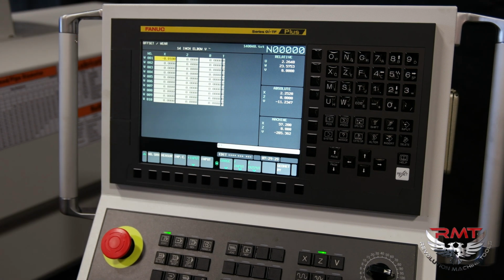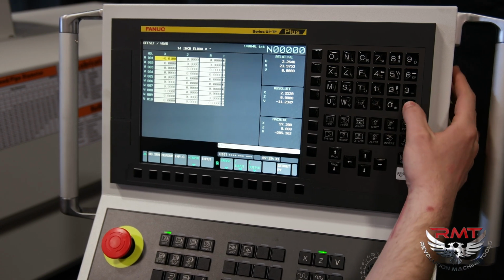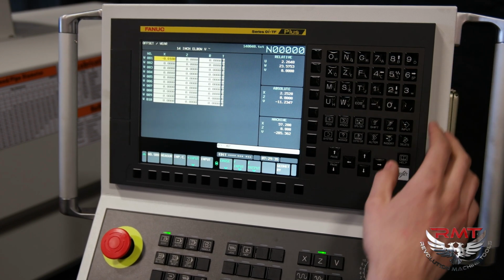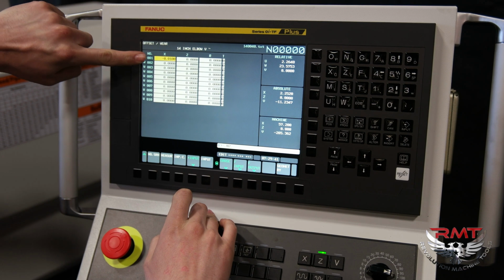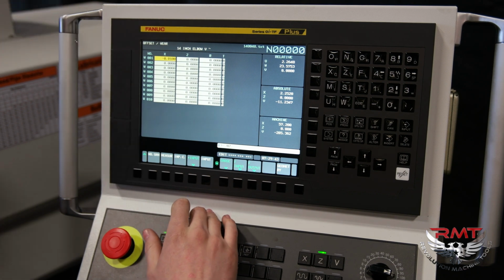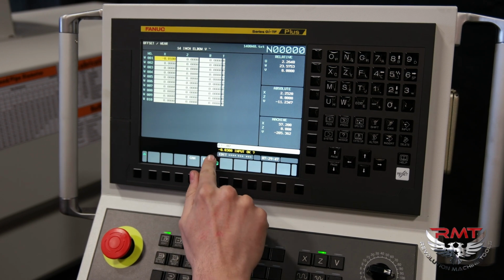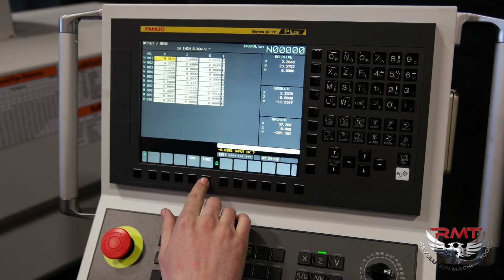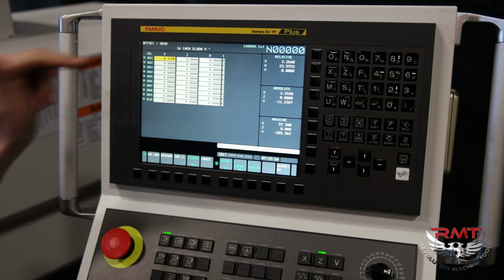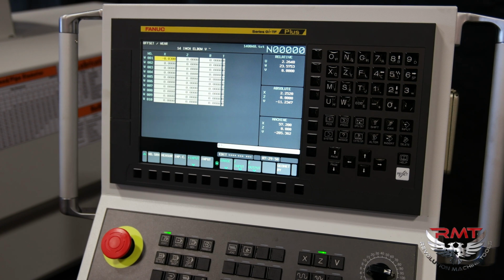However, it is a better habit to type in the number and then select plus input. This will take the current value in the highlighted box and the number typed out, and it will verify that this is the number you are striving for. Then hit execute, and it will now update to 30 thousandths instead of the 20 thousandths that I had entered.